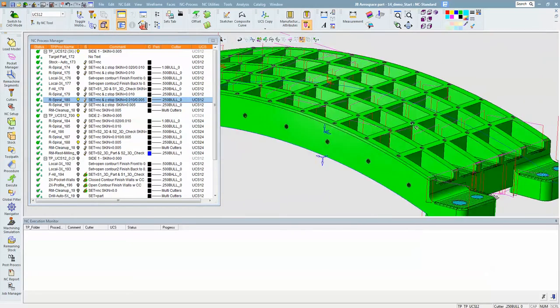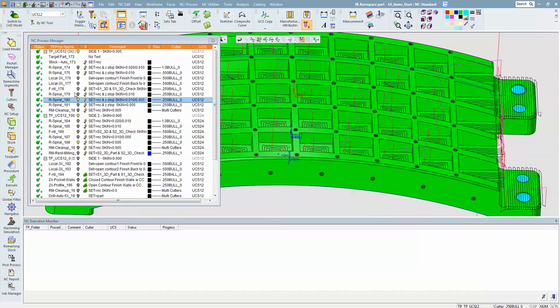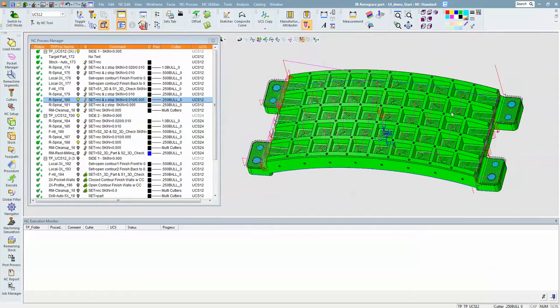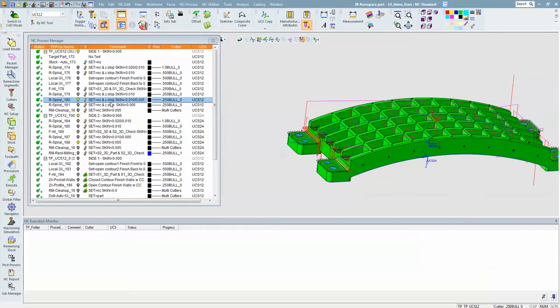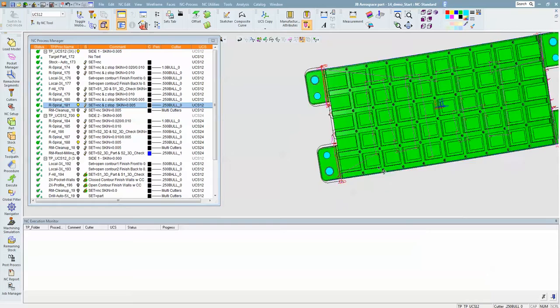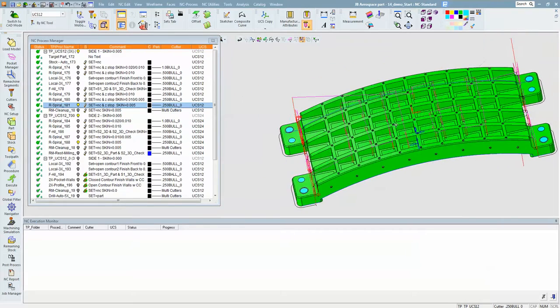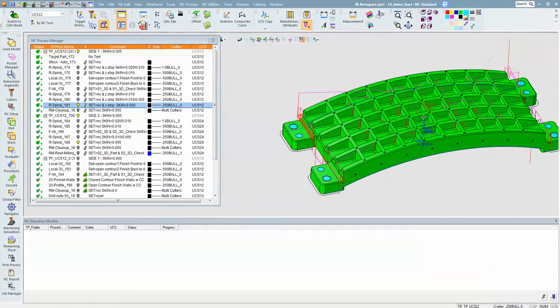Then this is basically a copy and paste of that procedure, where we just change it to floor milling. So it goes in and it's cutting the walls to within 10 and the floors to within 5. So it's basically like a floor milling procedure. And then we go from 10 on the walls and 5 on the floors to just 5. And again, this first tool path, we're not taking it to 0, for like stress relief type conditions.